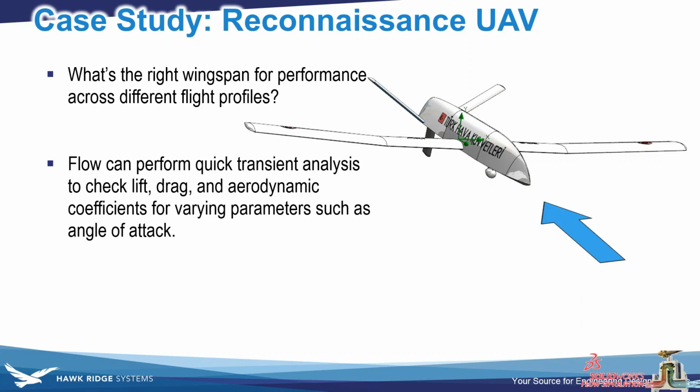We could simulate an acceleration condition at cruise. Or we could simulate something like changing aerodynamic angles. For example, if you were doing a wind tunnel test, you might run a lab test where you change the angle of attack of your aircraft so that you can study how lift and drag are changing as you rotate it through that pitch angle.